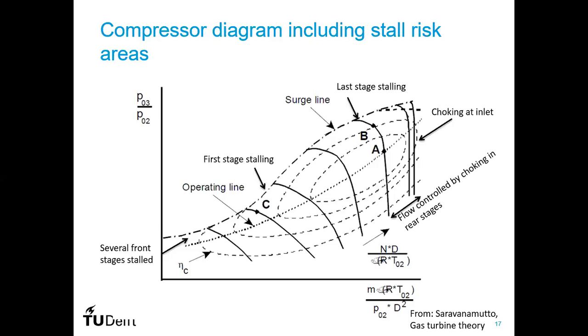In reality, if you look at single shaft gas turbine performance, you have all kinds of correction curves for inlet temperature to correct your power and efficiency to the ambient temperature. But the real story is that you run a little differently on the compressor map, and a little differently on the turbine map, and there are more effects of ambient temperature, maybe a little more heat loss, things like that, that are not included. In these simple calculations, we don't correct for the ambient temperature, but in reality, you should, of course.